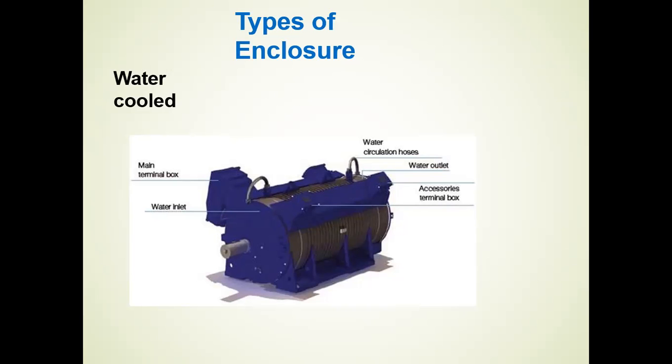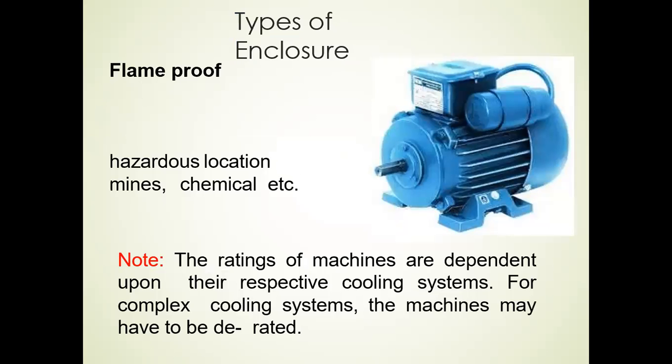Then one more, flame proof or explosion proof, for the use in hazardous locations such as mines, chemical factories, stores, etc. It may be noted that the rating of machines are dependent on their respective cooling system. For complex cooling system, the machine has to be derated.